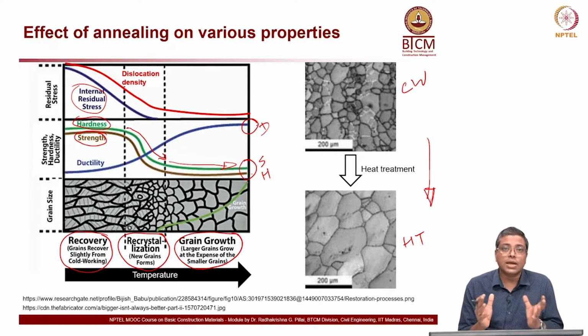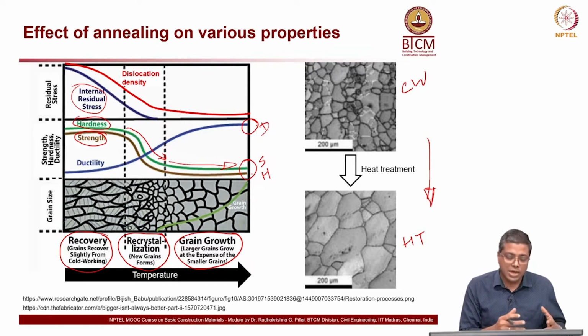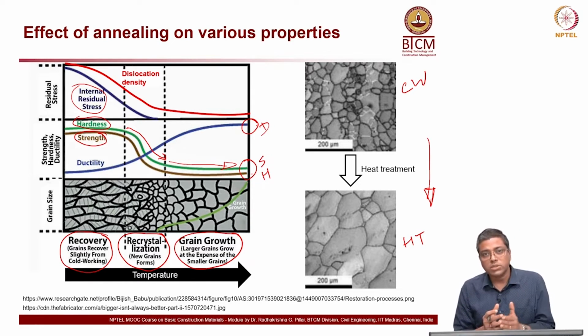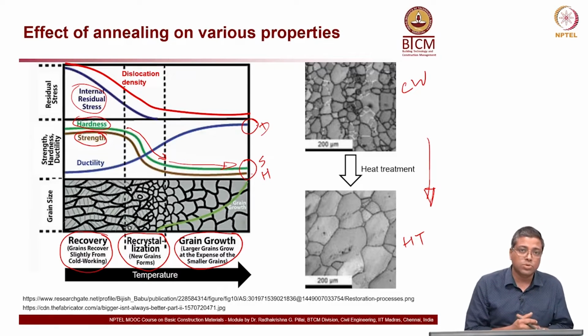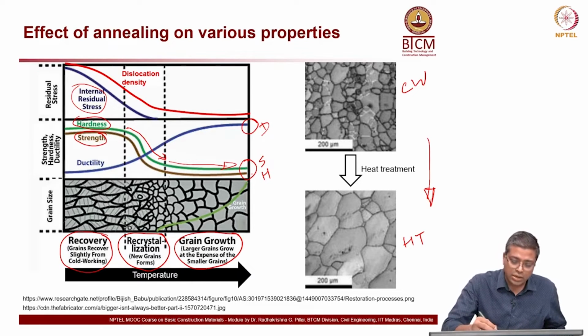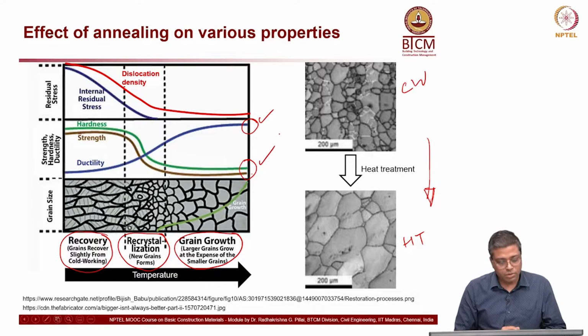All those target values for these properties will be given at the time of design, and then the steel manufacturer has to adjust the composition of the material, I mean the raw materials which are put in the molten material, and then the manufacturing process, the cooling rate, or how many times you do these heating and cooling treatments, etc. All that has to be fine tuned so that you get these target properties. Okay, this and this.